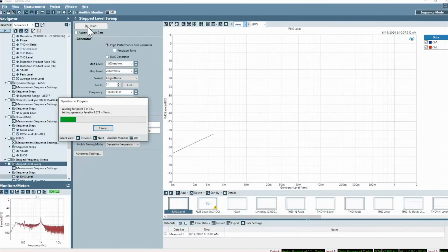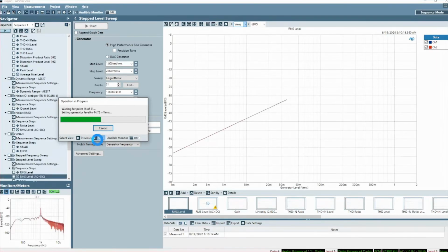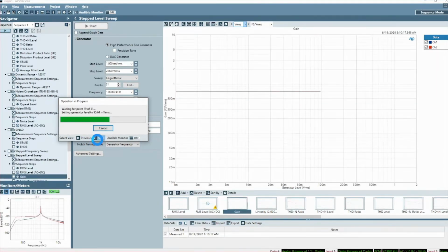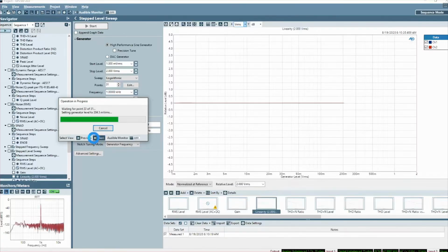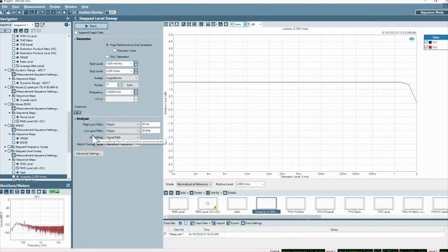The main thing we're looking for when we test any converter is this particular graph isn't so exciting. But here what we have is an amplitude linearity graph. And what we're looking for here is the range over which the gain function of this converter is flat or linear. And what you can see is just above 1 volt is where we get to the clipping point of the converter, and that's where it becomes nonlinear.